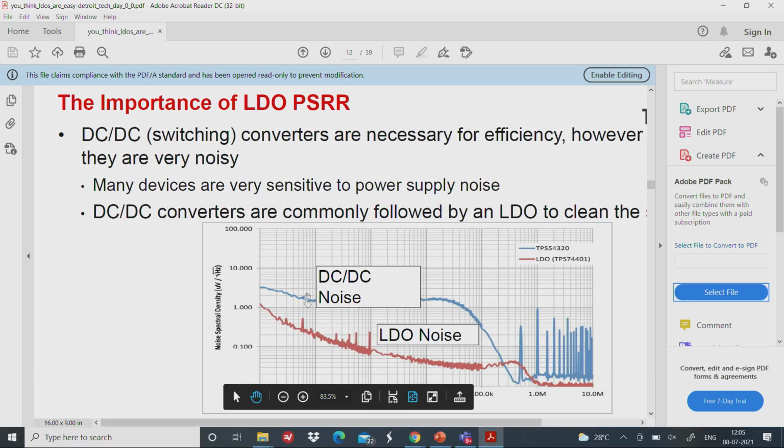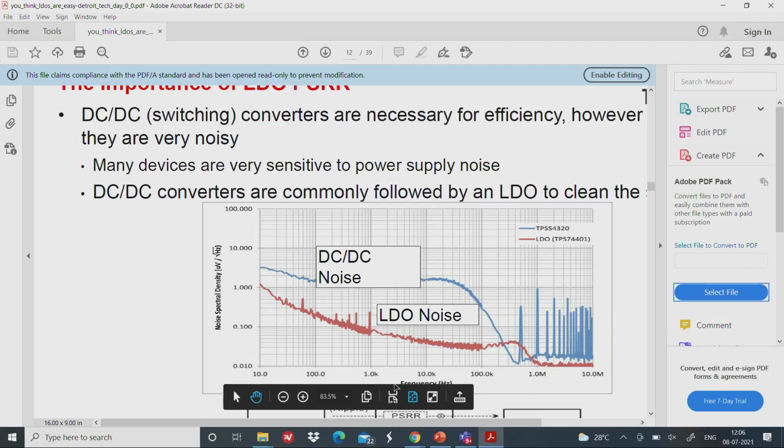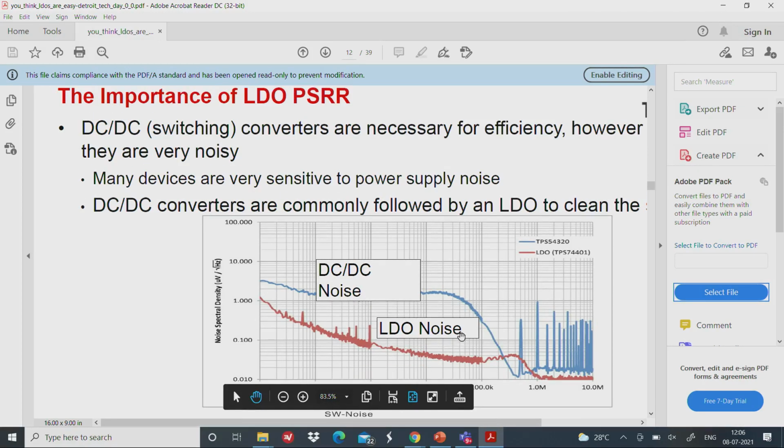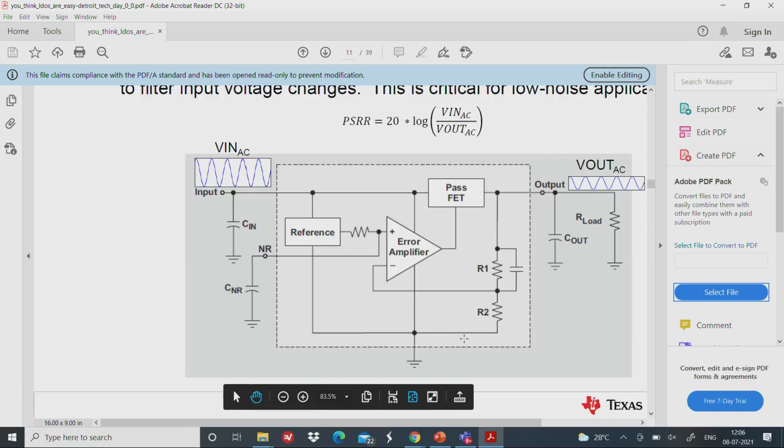First of all, remember, this is a log plot. The best way would be to do all your buck conversion from higher voltages to almost what is required using DC-DC, and feed the output of the DC-DC to an LDO, essentially this configuration.